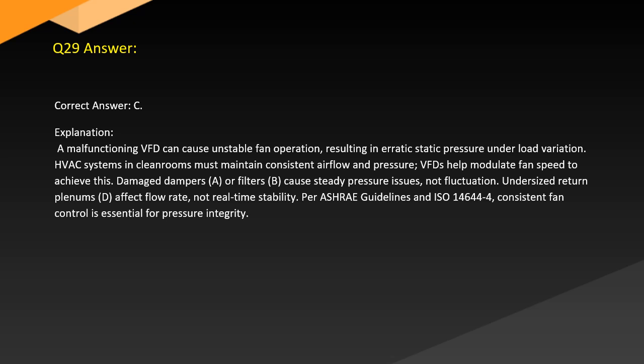Answer. Correct answer: C. Explanation. A malfunctioning VFD can cause unstable fan operation, resulting in erratic static pressure under load variation. HVAC systems in cleanrooms must maintain consistent airflow and pressure; VFDs modulate fan speed to achieve this.